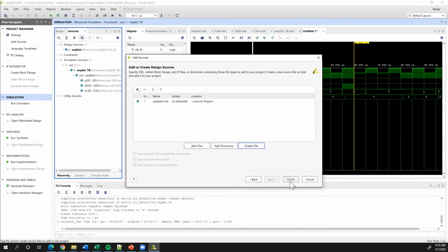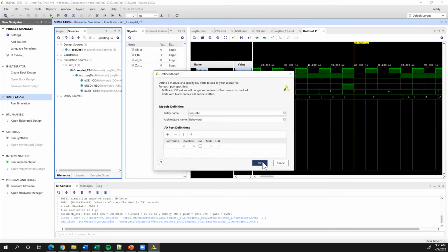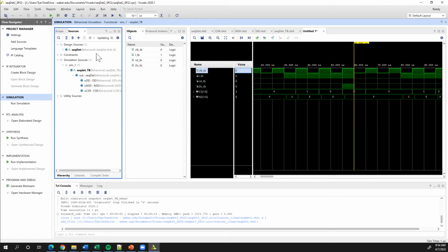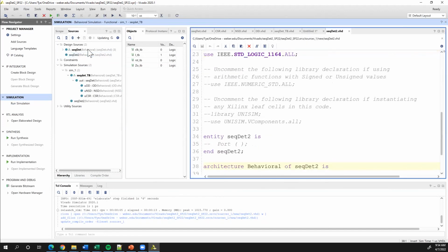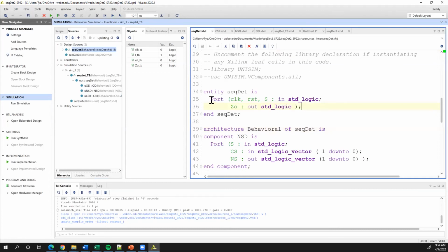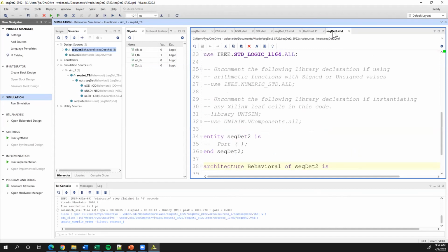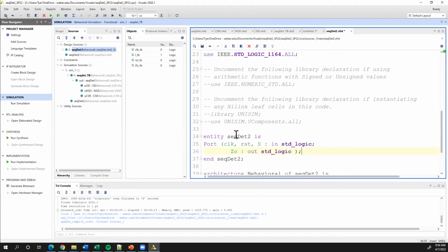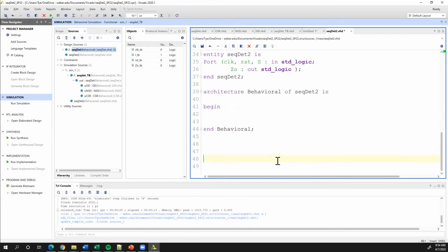So I'm going to make a new file. The first thing that I'm going to do is use the exact same ports so that I don't have to change my test bench at all. And then we have to introduce a bit of a new idea, which is how we're going to address the problem of what happens if we have a million states, and I don't want to sit and assign state codes to all of them. We also want something like constants, right? Because there are better ways to call a state than 0, 0, 0, 1. We can kind of tell what they are, basically.